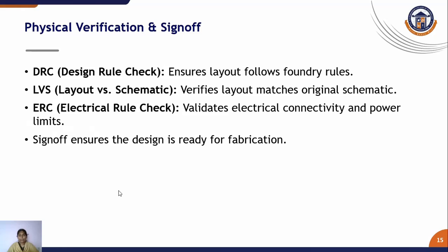Before this, first we designed the Verilog code. The Verilog code is converted into a circuit diagram. The circuit diagram is converted into layout form. Once we convert to the layout form, again we can verify the functionality of the layout with our original schematic. That is named LVS.